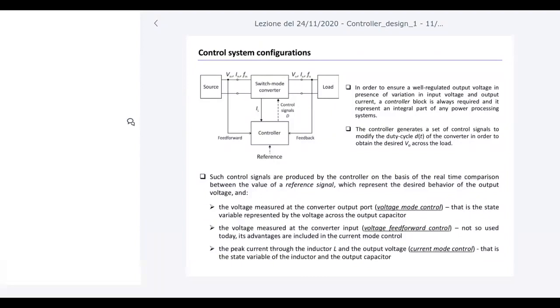For example, in cyclostationary condition, we derived the properties of the basic switching mode converter topologies. We derived the conversion ratio of the buck, boost, and buck-boost converters. And in that situation, we derived the peak value, the root mean square value of the current, the electrical stress of components, etc.